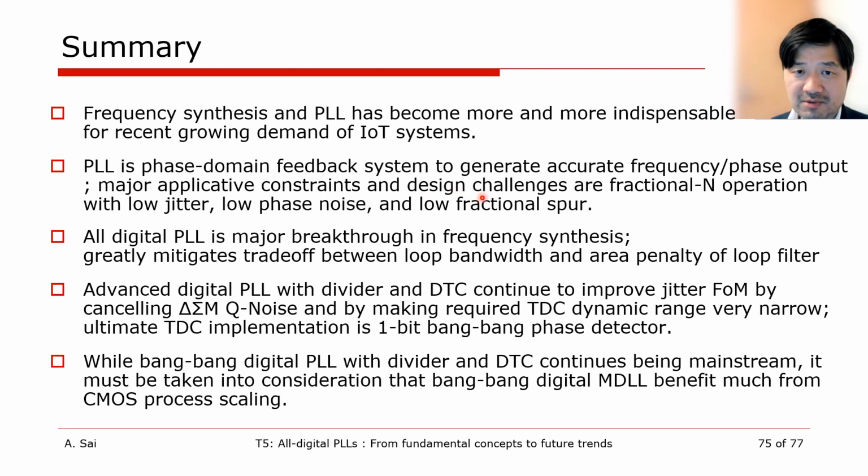Major application constraints and design challenges are fractional-N operation with low jitter, low phase noise, and low fractional spur. All digital PLL is a major breakthrough in frequency synthesis, greatly mitigating the trade-off between loop bandwidth and the chip area penalty of the loop filter.